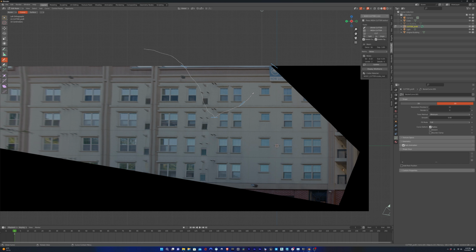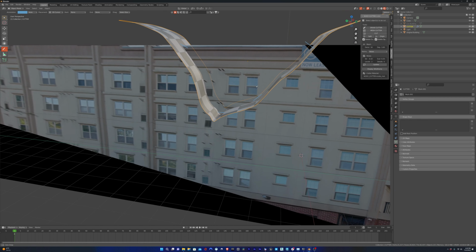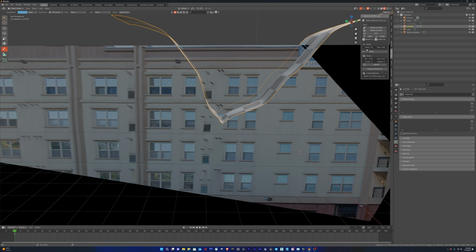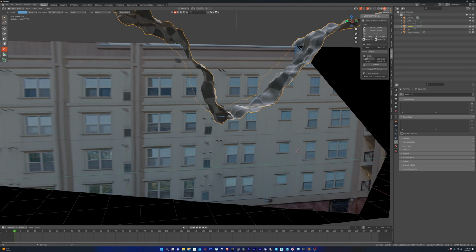So go through that, and then up and out this way. Tab out of that, I'm going to hit Mesh Cutter, and you can see that we've created that cut again. And then one of the things that I can do here is actually increase the strength and then decrease the scale a little bit and hit Update. And you can see that that made it a little more rough. That noise pattern's a little too strong. So for the strength, I'm going to maybe go down to 0.8 and then update it again.